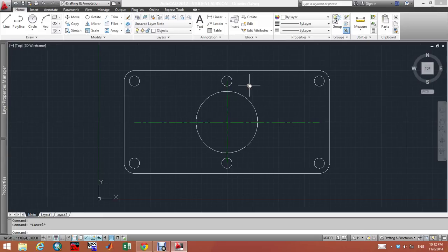Okay, so once I'm done, I can start drawing another center line from here to here, this time going to be, let's say, 2.9 units. So I'm gonna launch the offset tool, and then I'm gonna specify the distance at 2.9. Okay, hit enter. I'm gonna do this again, 2.9, and then specify this one to put it here, and then I'm gonna change this one to the center line layer, and then at the object layer I'm gonna start drawing the circle.